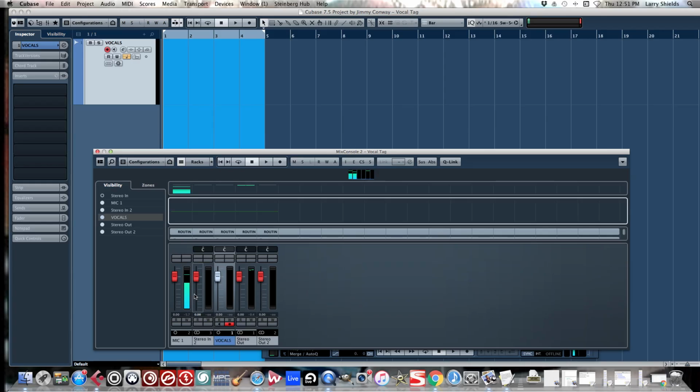You don't want it too low and you don't want it too high where it's peaking. All right. You want a nice sweet spot. Right now I'm at a nice sweet spot. It's at, I think, negative 4.6 dB, which is pretty good. And when you record here, this is the input that it's recording onto. This is what's showing me my level. So when I record, I don't clip and I don't overdrive my signal when I record it onto tape. And when I record onto tape, this is my tape right here, or this is my audio track that I'm going to record onto.